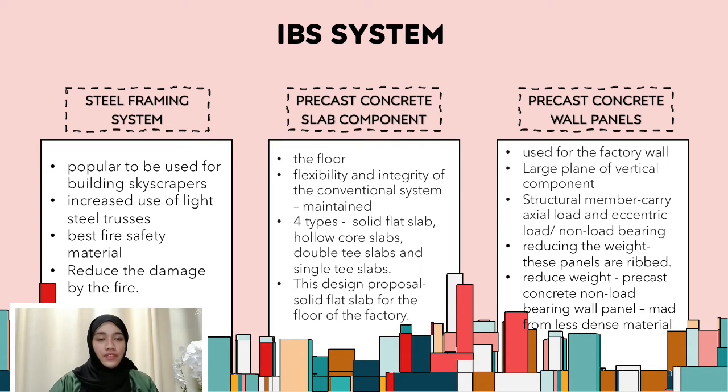For the interior of the factory floor, we are using the precast concrete slab component. The flexibility and integrity of the system are still maintained even with the precast concrete slab used in the half slab to minimize the traditional timber formwork. Precast concrete slab components are joined together and connected to form a large slab.